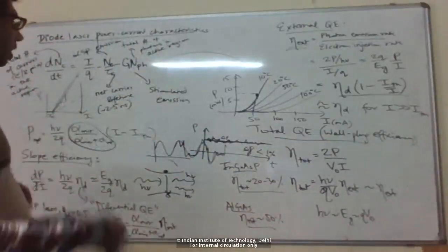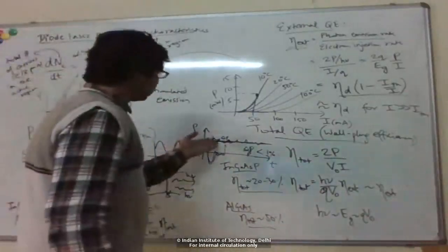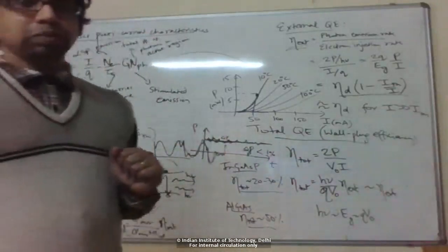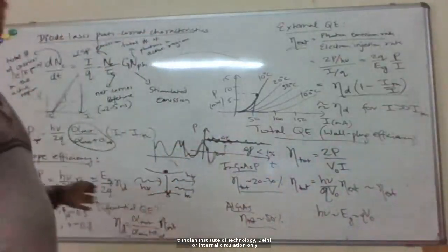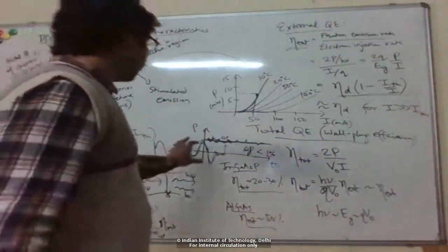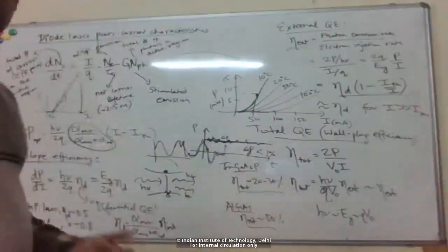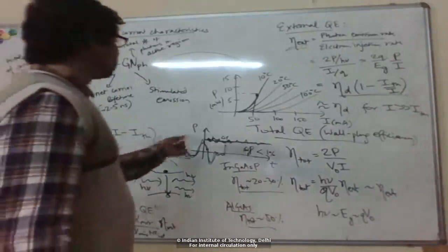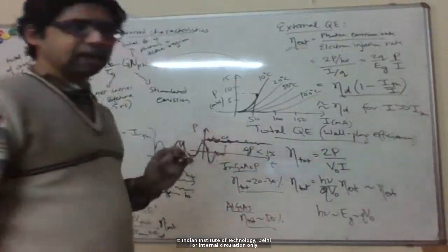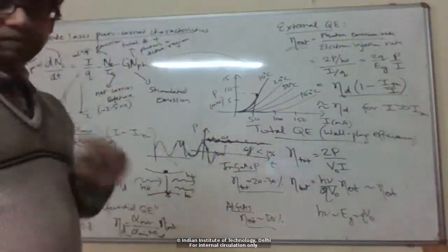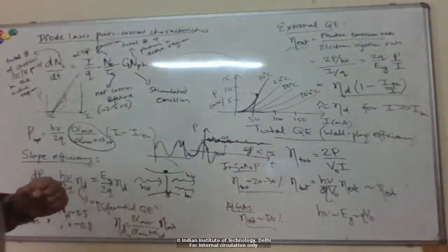There is some noise, right? So all these factors will give you some noise in the optical output. But let's say you eliminate all of that. Even then, finally, you will be left with spontaneous emission, which you cannot get rid of. It's like a fundamental quantum effect. And so the minimum noise you can have, or the minimum laser line width you can have, will be determined by the spontaneous emission.